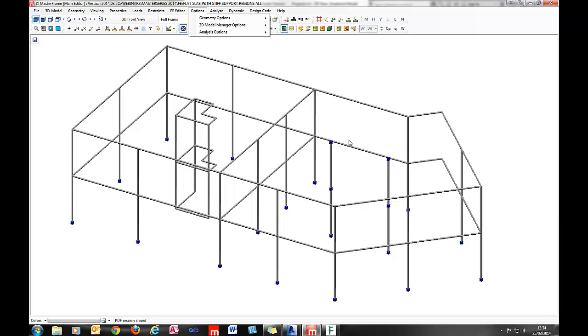Previously, of course, slabs and walls are all connected together. However, the zone of interaction between a column and a slab was done just through the nodal connection. Now that presented some quite interesting challenges when we would then go through to the analysis stage. You would get quite high moments occurring around these peak points, points of singularity. And we still have a very good way of dealing with those called peak smoothing.